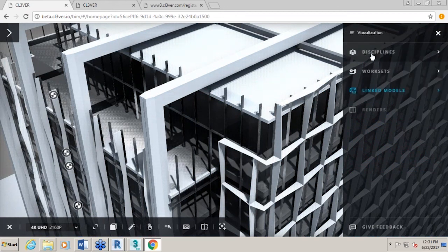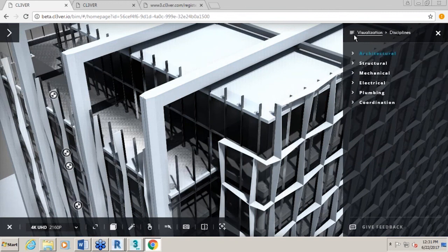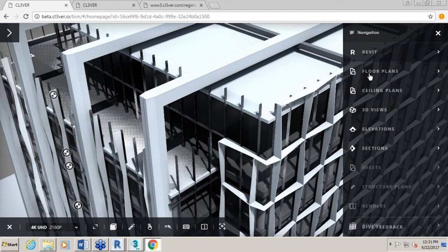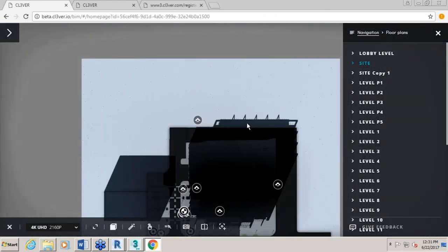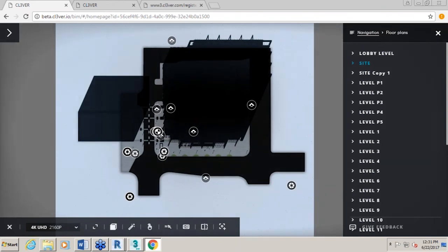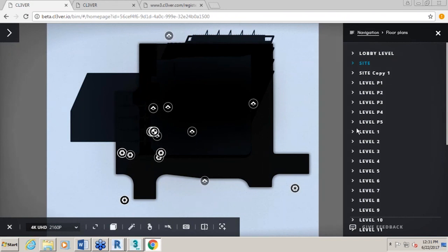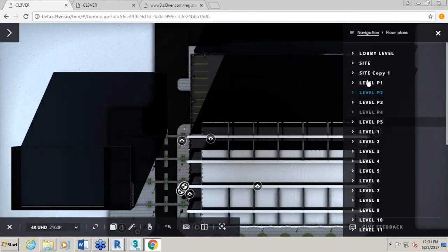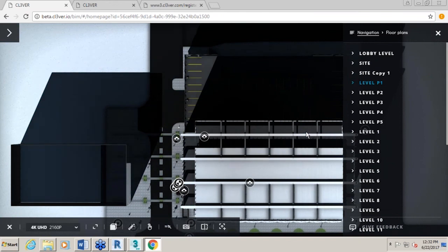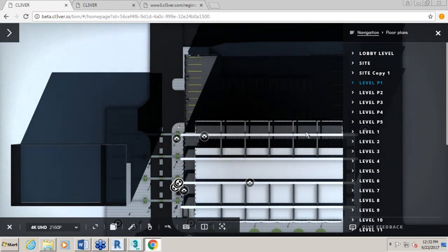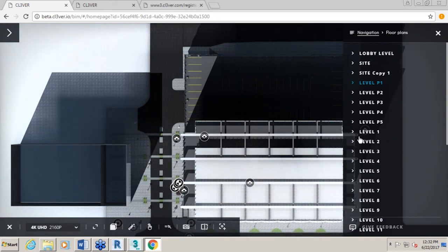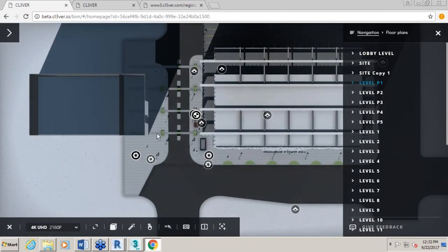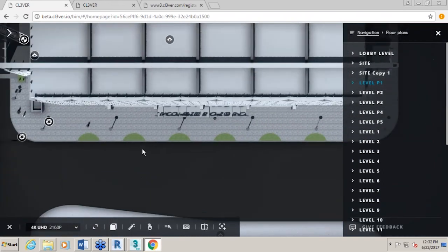Can CL3VER load in context such as Google Maps of the buildings around the model? In the version of the presenter, a user will be able to use a live link directly from Google Maps to show on-site location. Yes. Great. If you have topography like what we've done, and this is not a good example, but what we've done before is, we'll create a piece of topography, we'll put a diffuse map material for that like a capture from Google Earth, just to have it show up on the plan in Revit, and that'll carry through because it'll carry through the diffuse material. So you could go to the plan, if you had topography, the same way you see the streets out here, right? You could do that currently.